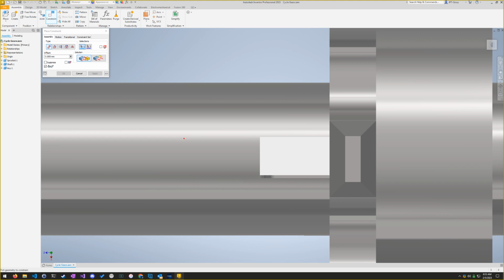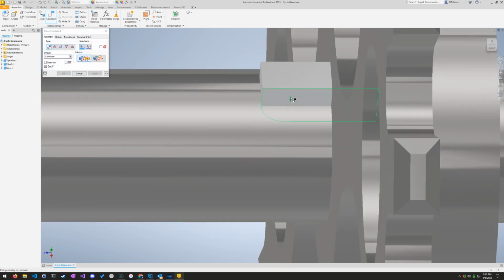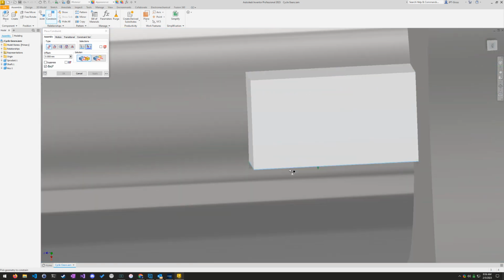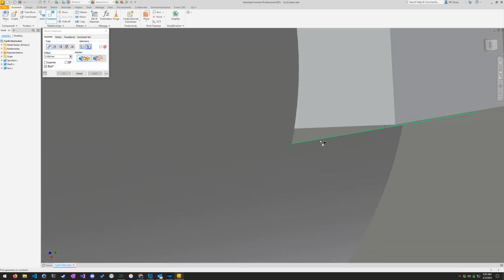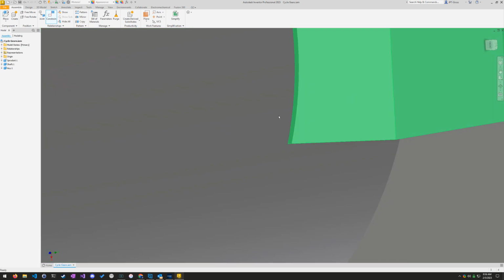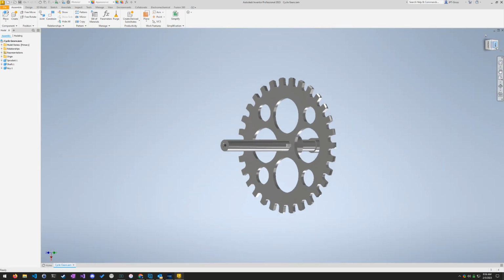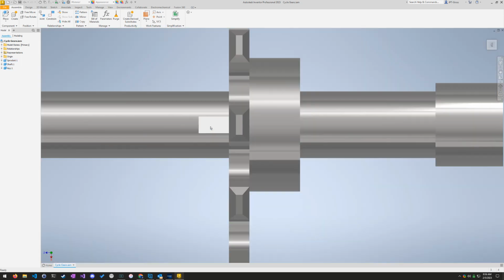So when we do this mate, what we're going to have to do is say that I want this face, and now we can do a face, to line up with the face on the inside. I want it to touch this. When I click OK, now this thing is seated perfectly where it's meant to be. It's perfectly in that slot.